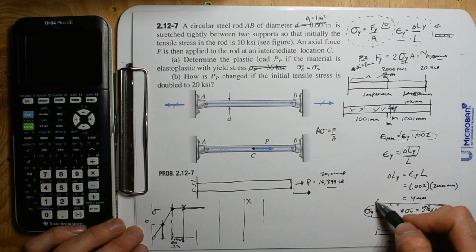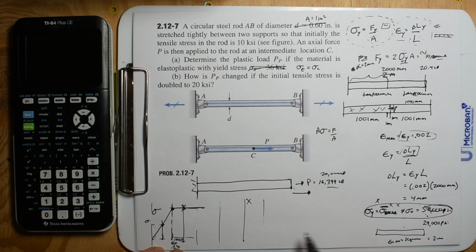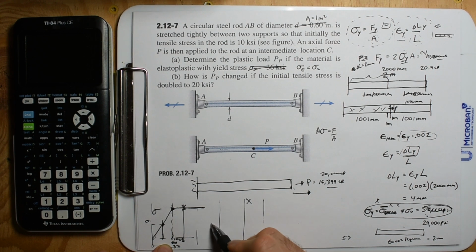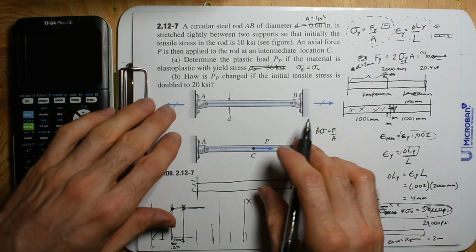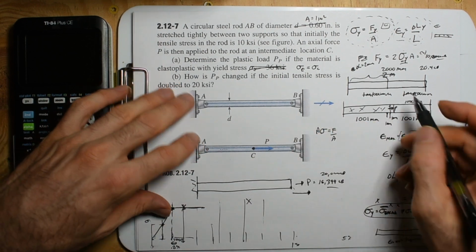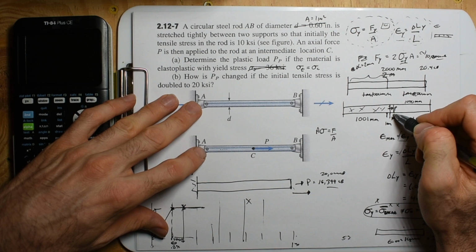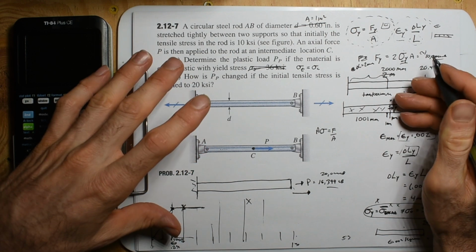You'd be way over here, since steel can stretch 5%. 25 times as much as this 0.2. Because this is 0, this is 0.2, we would go 3, 4, 5, 6, 7, 8, 9, 1%. That's 1%. And then you'd go another 2%, 3. So you're off the page of how far steel can actually stretch. So this little extra 1 millimeter is such potatoes.